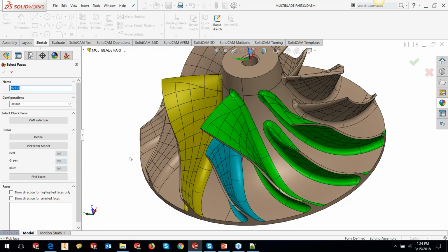This error comes from those surfaces which were not created using the revolution technique, but were generated using some patching up or NURBS-based technique. The only way to check them is to create an offset of this surface, or rather a copy, and untrim the surface to see if it is really generating a revolved surface or some crazy surface. When you don't have a surface of revolution on the multi-blade geometry, you will get an error saying that it's unable to extract the hub surface. In that case, you will have to manually create a curve and revolve that to generate the surface and define that surface as a hub surface.